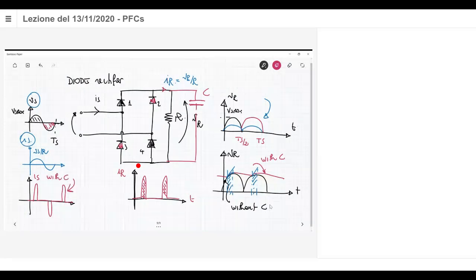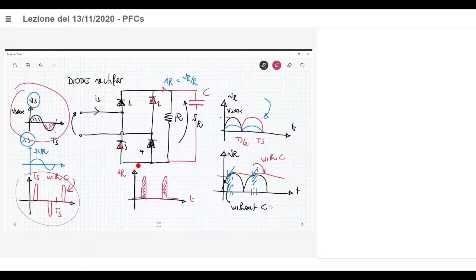As you can see here now, the voltage at the input is a sine wave, but the current is not a sine wave, it is distorted. In that situation, your power factor is reduced because it only depends on the product of the fundamental of Vs, which is just a sine wave, and the fundamental component of the current Is.